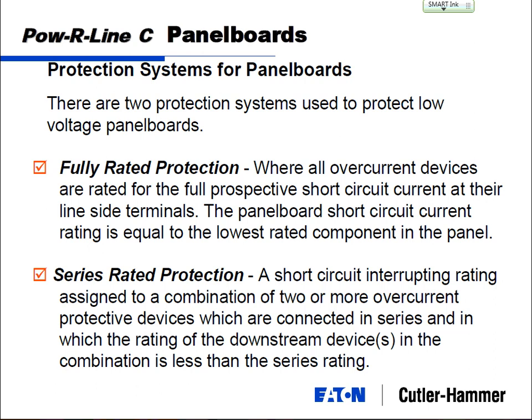There's a slide coming up, but basically when we talk about withstand, you can flow 10,000 amps through these breakers. They're going to let it flow through, and they're not going to blow into pieces. They're going to be able to do the next job, which is actually interrupt the fault current.